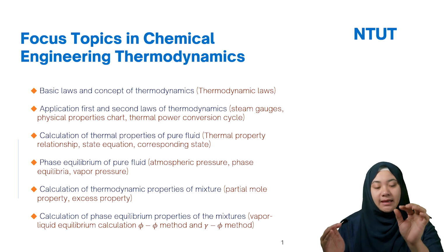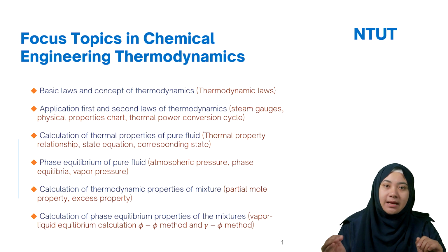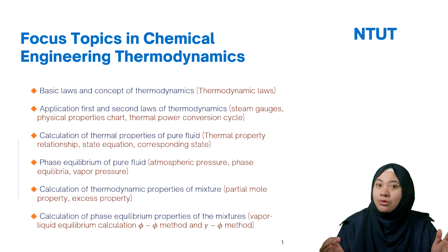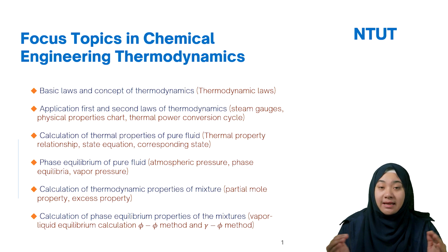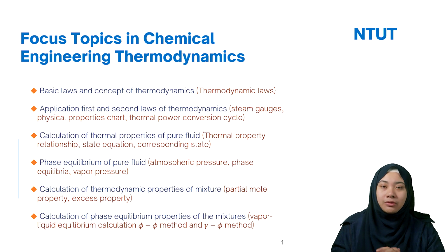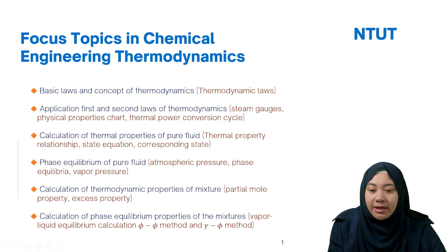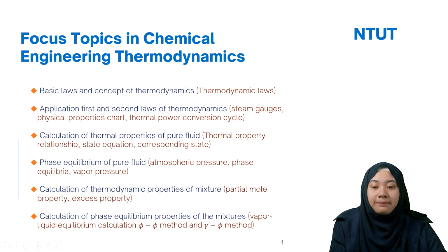So in this case, the highest point we define as the critical point, where the phase between the vapor and the liquid phase, you cannot distinguish each other. So if I would like to separate two mixtures, but I operate at the critical point, I couldn't separate these two phases. So in this case, we need to know the thermal properties based on each characteristic of the pure fluids.